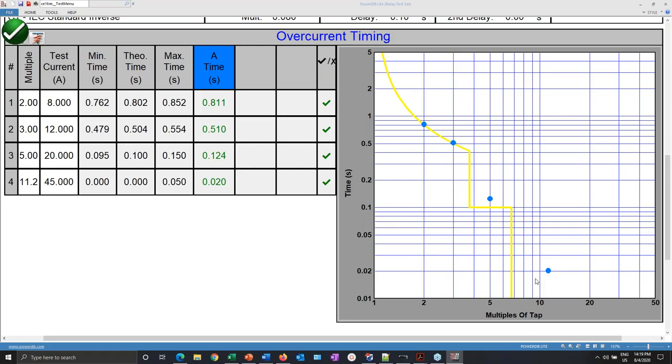And sometimes it's overwhelming, the amount of overcurrent relays and elements that you have to test in a single substation. So having a tool like this is very useful. And you have some relays that have a composite characteristic that looks exactly like the one that I'm showing you here, where you have the 51, the low set and the high set instantaneous all in one, and you can test them all in the same, let's say, screen with RTMS.